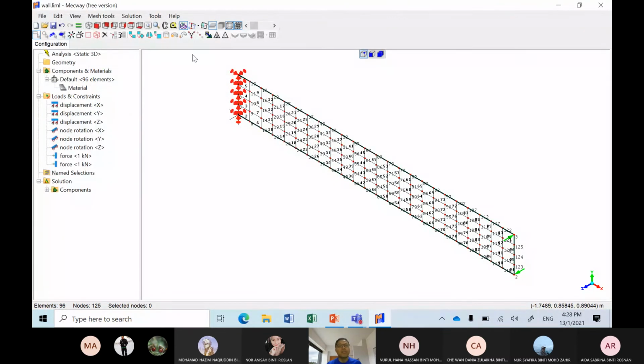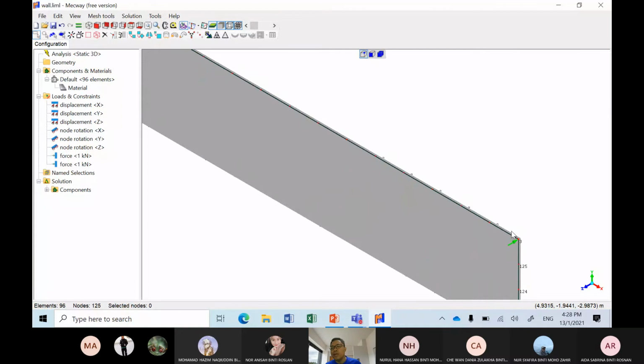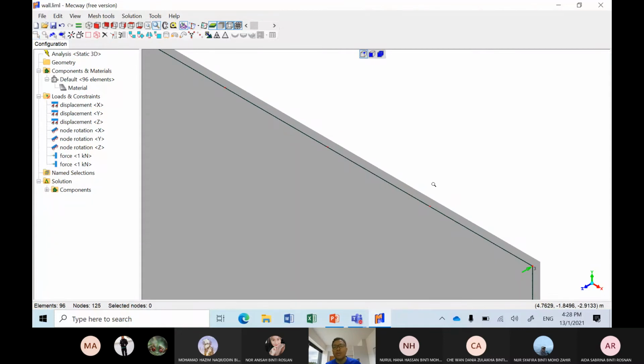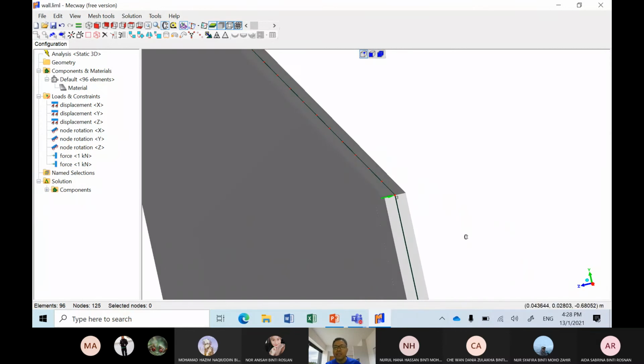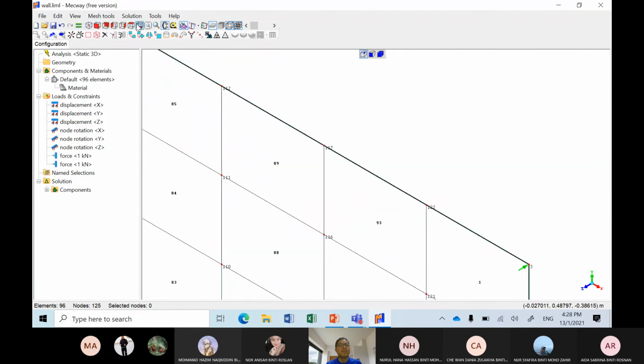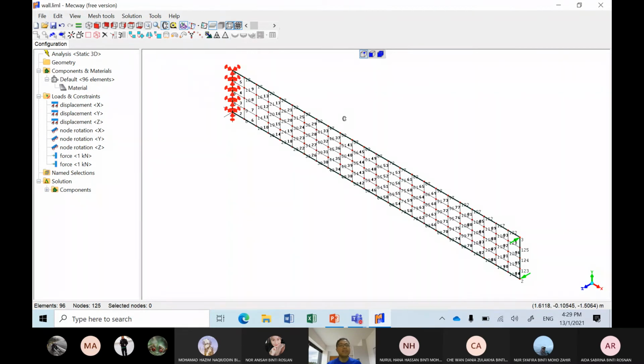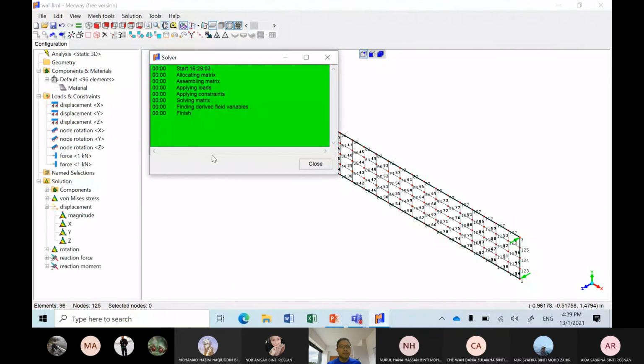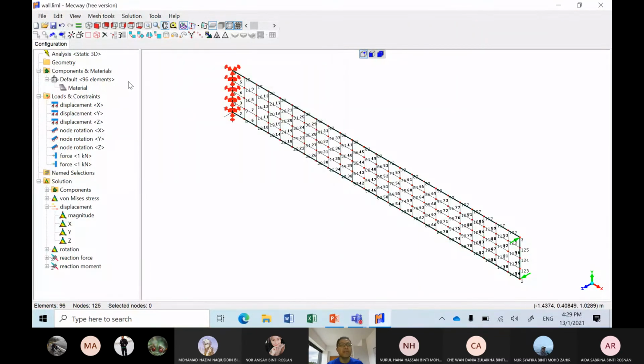Okay, before you run, you may want to see the thickness. You can click this show thickness. Sorry, this part. You can view that the wall has its own thickness. If I rotate this, the thickness of the wall from this point to this point is 50 mm. Okay, we run this. Hopefully, okay, before doing that, I did not remember. Click this analysis, change to be CCX, calculix.